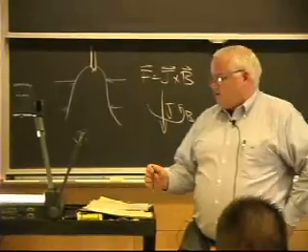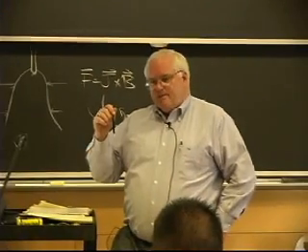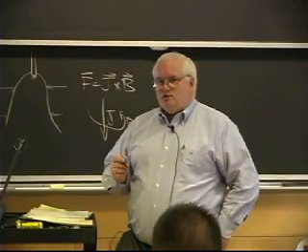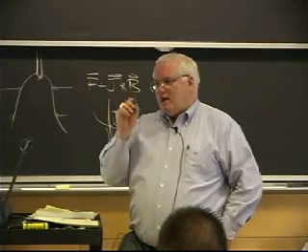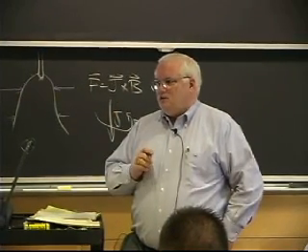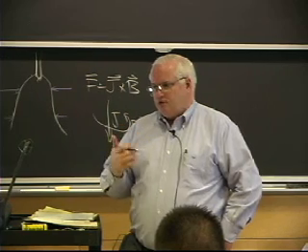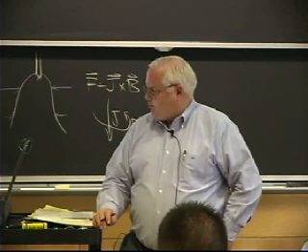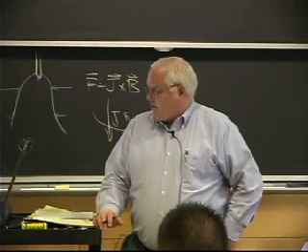aluminum and you're using gas tungsten arc welding, sometimes you will melt off the tungsten tip, and he used to remember seeing rectangular shapes of the tungsten inclusion. Tungsten doesn't melt, doesn't alloy with aluminum significantly because of the difference in melting points and relative solubilities.